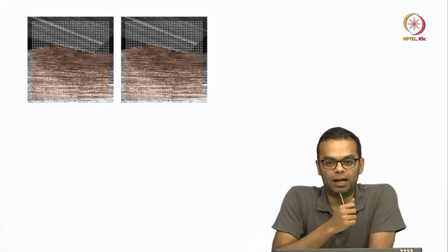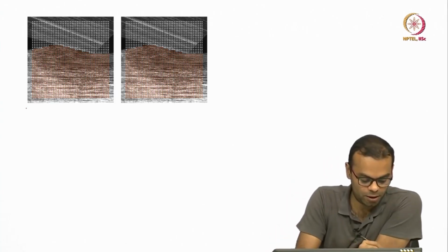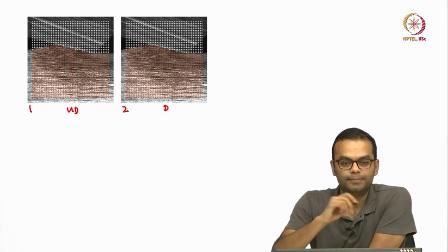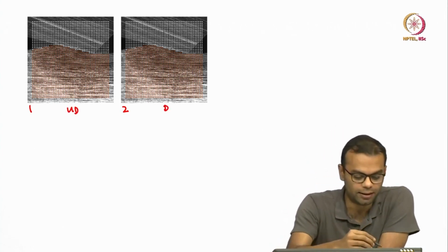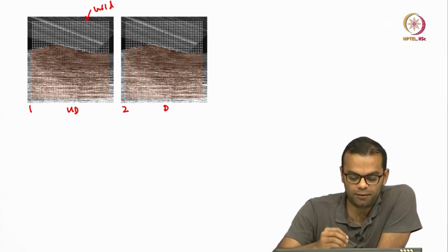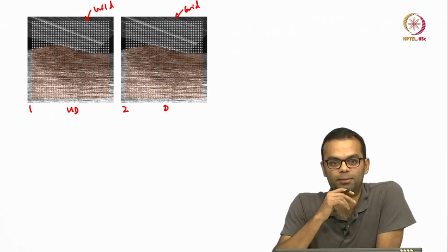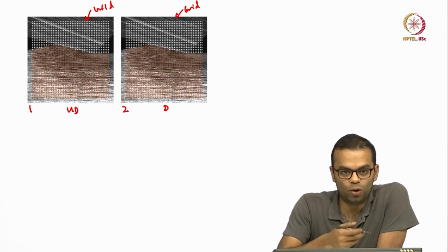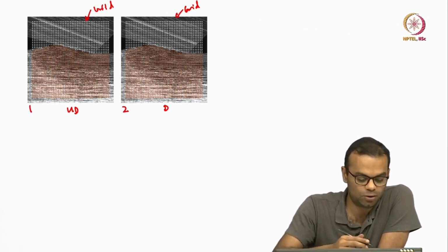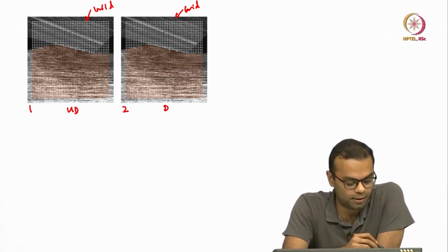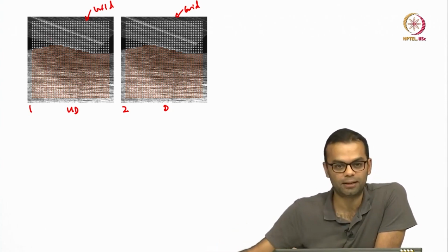Okay. So, here is how a typical algorithm goes. Here is our image 1, here is our image 2, undeformed and deformed, and we have a grid. This is a uniform grid that is placed here, and we have a uniform grid also placed here. The second grid is a little bit superfluous, but nonetheless for completeness I am including it here. Now, in the grid we already know from the masked region which is the region of interest. So, we can multiply this grid with the mask again, and then in the white regions we do not have to do any correlation, and in the red regions we have to. So, that makes our life a little easier.